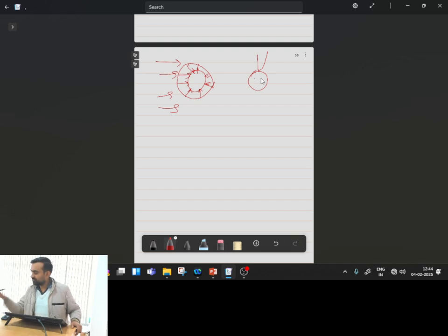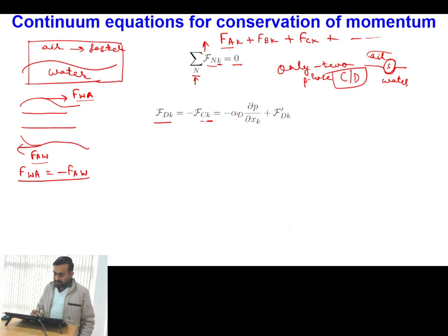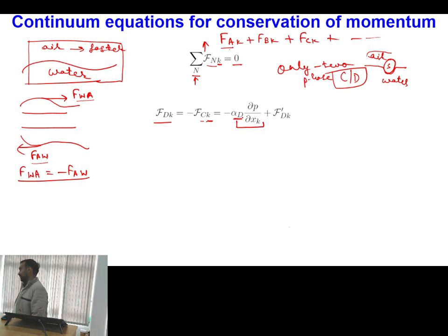Interaction forces, so that is what I have done. Now here you can see the first part represents the interaction force because of the pressure distribution, and as we are calculating this force on the dispersed particle, I am multiplying with the volume fraction of the dispersed particle.